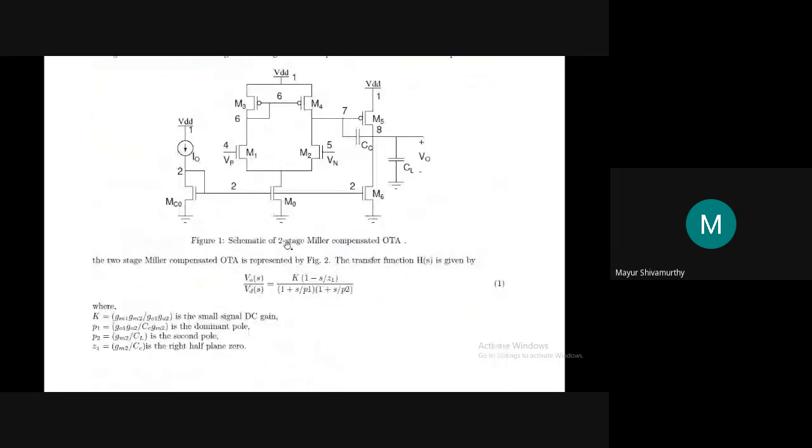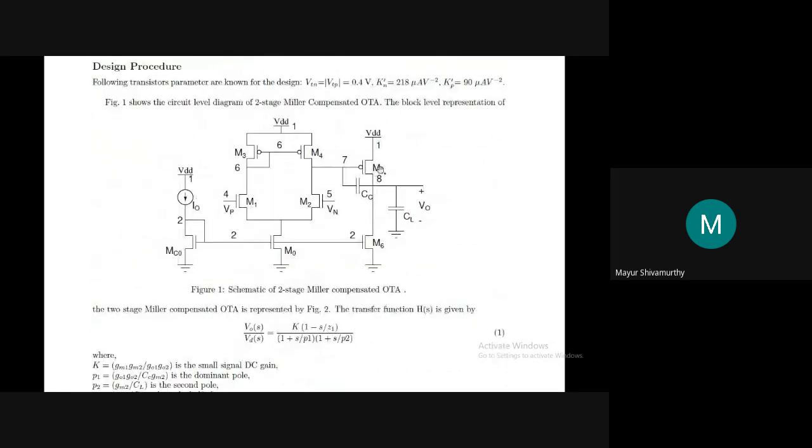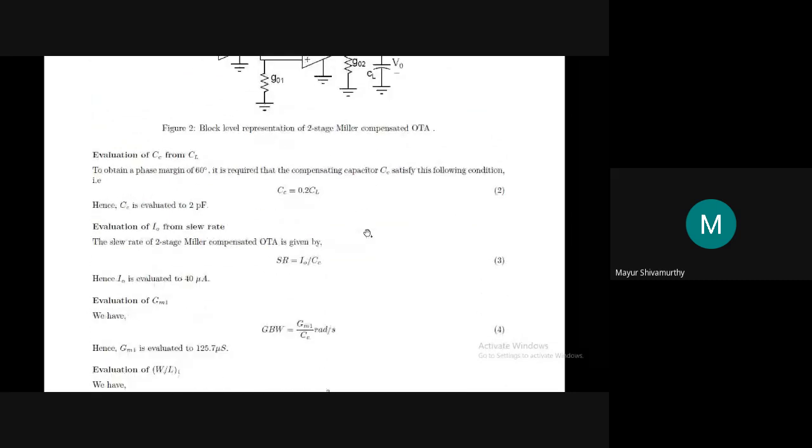So with this, we have identified the geometries of the first stage of the two-stage op-amp. Next thing is identifying the device dimensions of the second stage, our common source amplifier stage, that is identifying M5 and M6 dimensions. The rule of thumb is very simple.